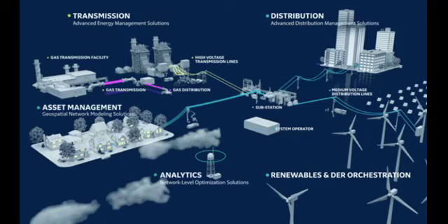Reactive power compensation. FACTS controllers can provide reactive power support to the grid, improving power factor and reducing the overall demand for reactive power generation from power plants. This leads to better utilization of generating resources.